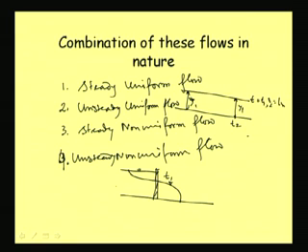It is also varying with space, with distance; here depth is different, here depth is different. Then at the next moment, at another time t2, this is again changing. So depth is changing with distance as well as with time. At t3 it may be coming here. So with time as well as with space this is changing, and we call this an unsteady non-uniform flow.